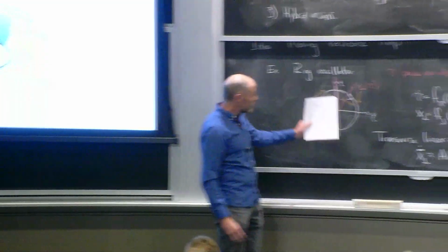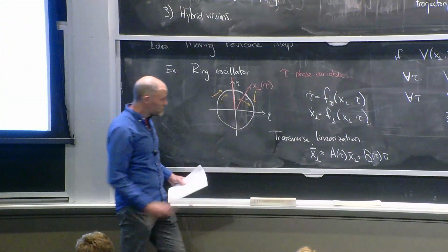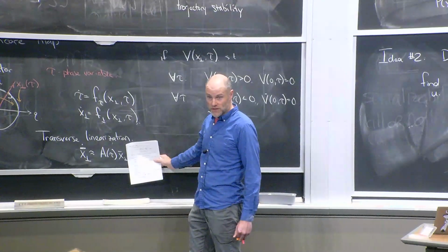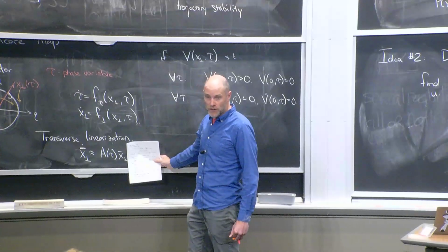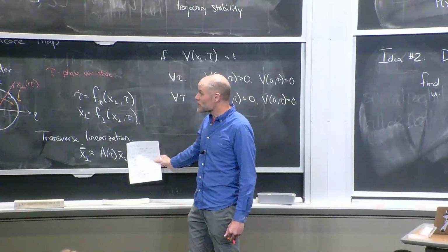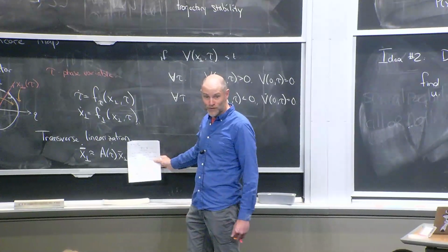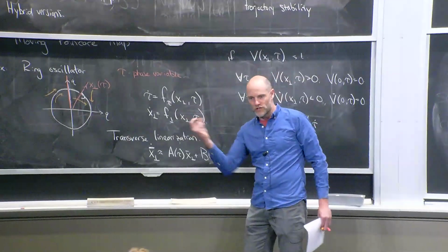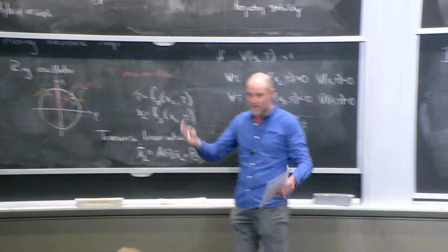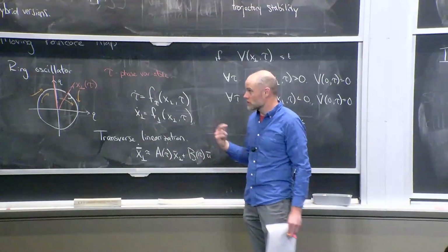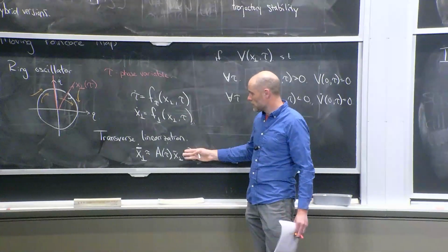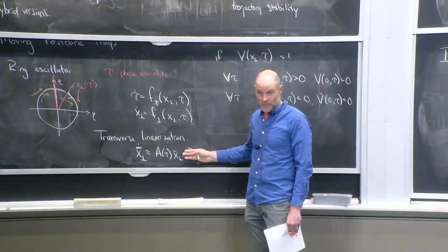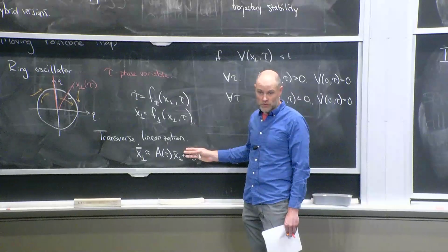Cool. So if you have a passive or a closed loop system, then you can get a transverse linearization that just looks like this. You can call your Lyapunov equation. You get a quadratic as a function of tau Lyapunov candidate, and it really does look like that, although it could stretch and shrink as it moves along. It doesn't have to be the same quadratic form all the way around because it's a function of tau, right? But really, it's the same tools we've already invented, but this time, it's doing orbital stability instead of trajectory stability.